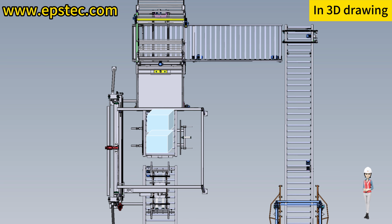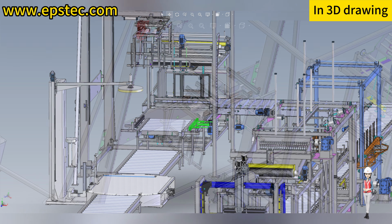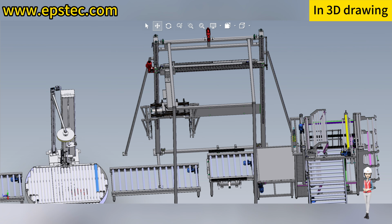After 2 packages are loaded, the stacking process is started using the alignment cylinder for alignment first. Once aligned, the stacking clamp moves downwards to the set height, clamps the 2 packages together, lifts to the set height, and then moves horizontally to the stacking lower conveyor area for sequential placement.